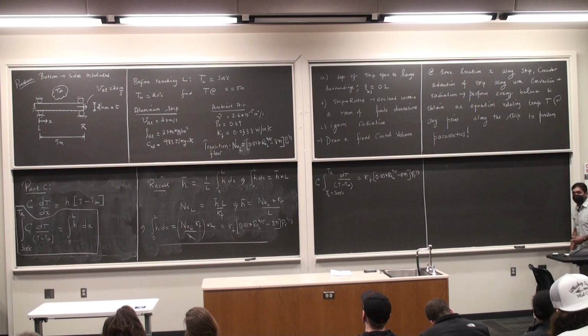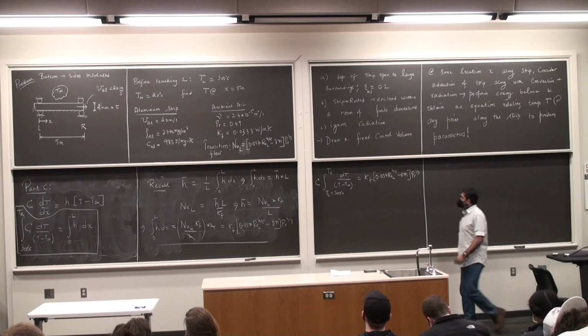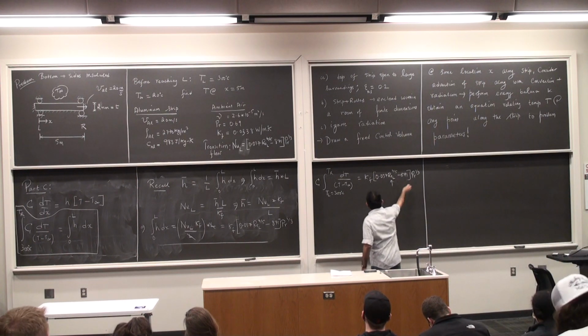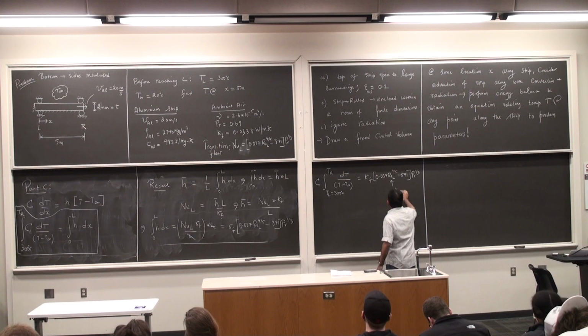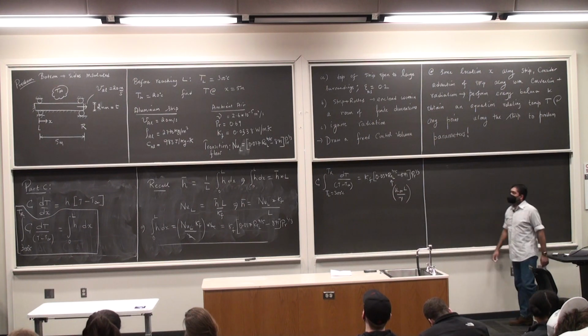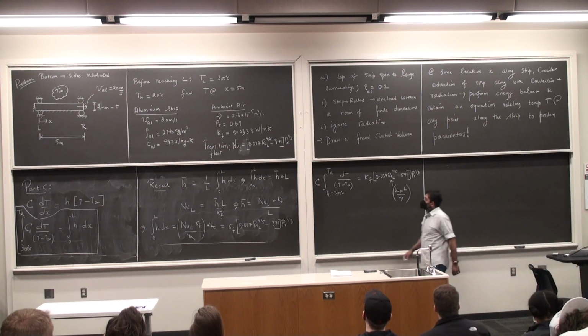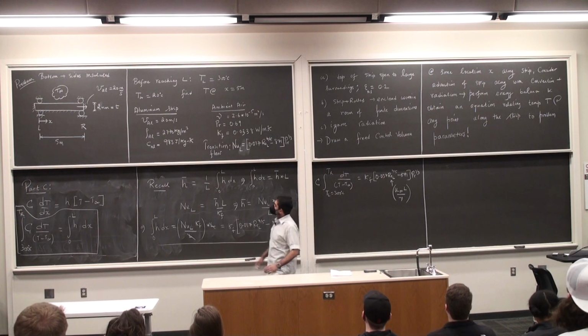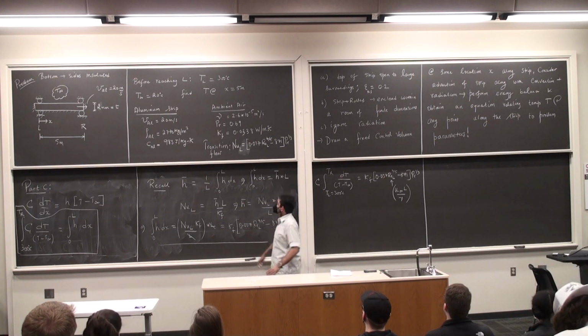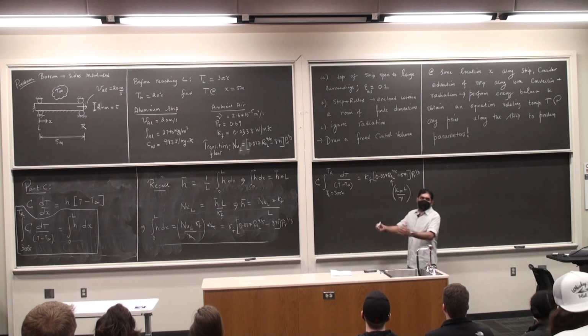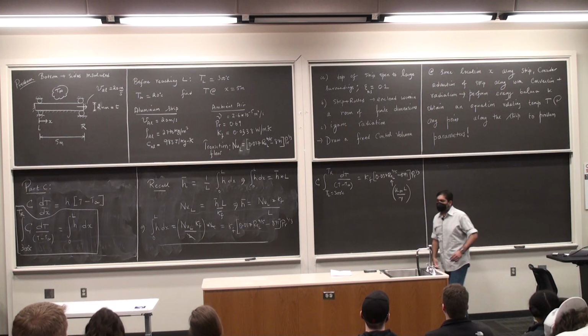Re_L is using the total length of the plate to calculate the Reynolds number. So this is just U infinity times L by nu. This is going to give me a logarithmic solution. And I had, I think, a negative sign for the character capital C, if you recall. So all put together, this is what you'll end up getting.